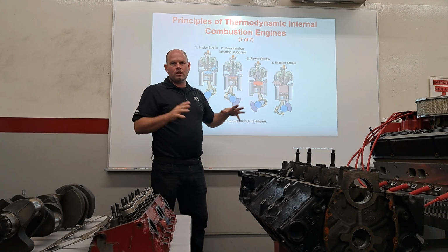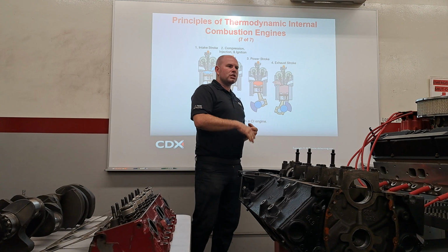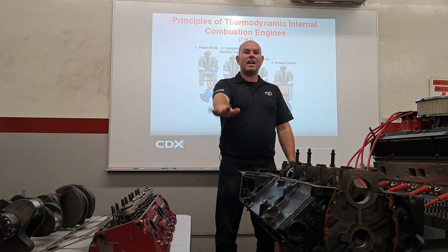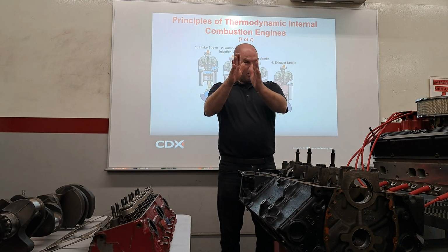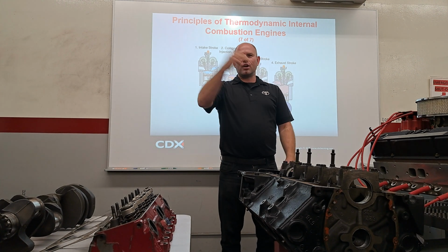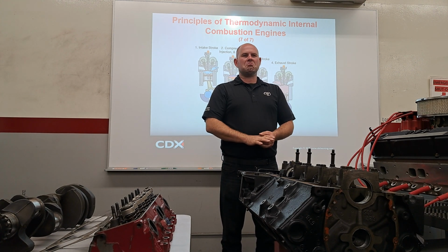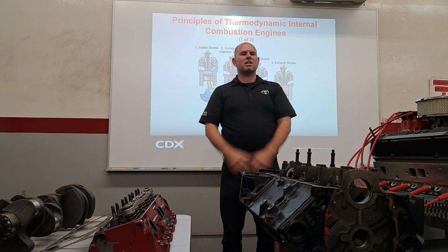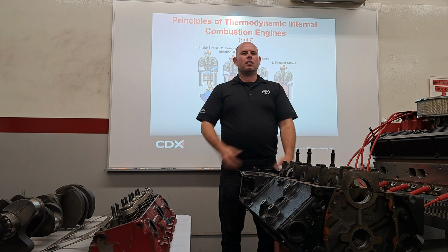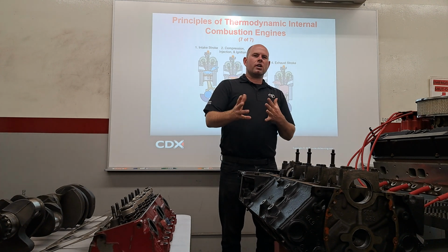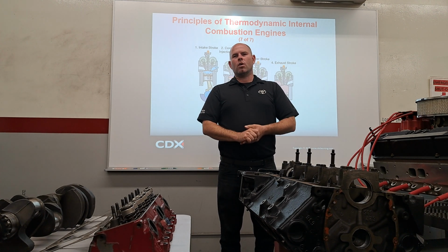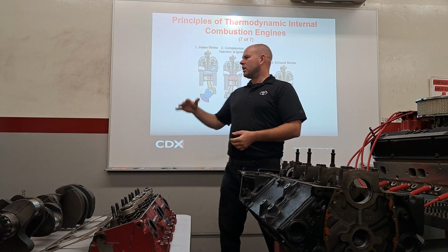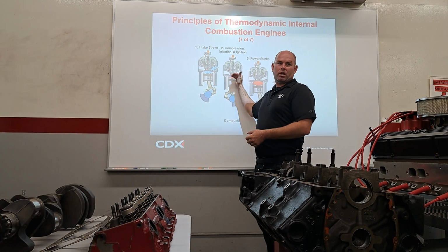On a gasoline engine, you hit the throttle, you hit the gas pedal, the go pedal on the right side, the skinny pedal. That makes air come in, right? A diesel doesn't even have a throttle. It's just sucking whatever air it can get, it's like, give me whatever I can take, I'll take it all. But what controls the RPM is how much fuel we spray. What controls exactly when the combustion starts is when we spray the fuel. Fuel being the diesel. Make sense?